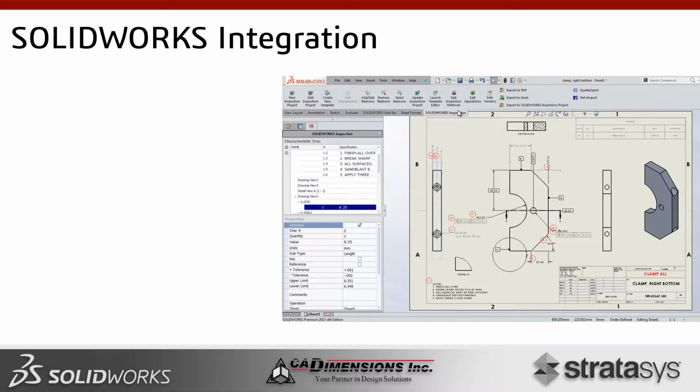So, SolidWorks integration. We only talked about the standalone product today, but SolidWorks also has the SolidWorks Inspection add-in. What this does is it'll actually go through and manually or automatically balloon all of the characteristics for you. In the standalone package, because you're using a PDF, you have to go through and capture everything.